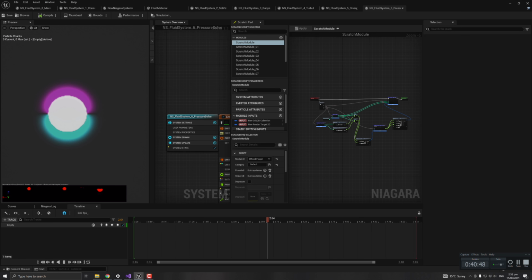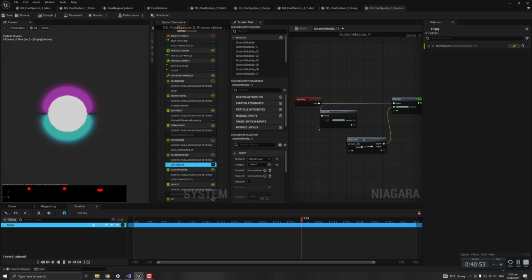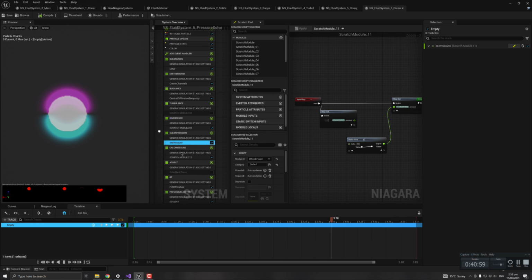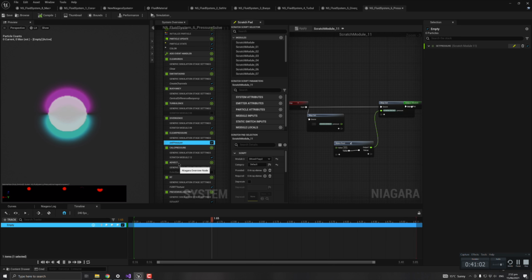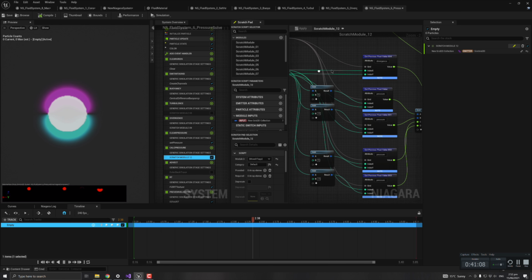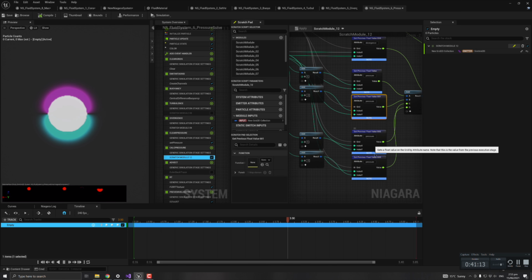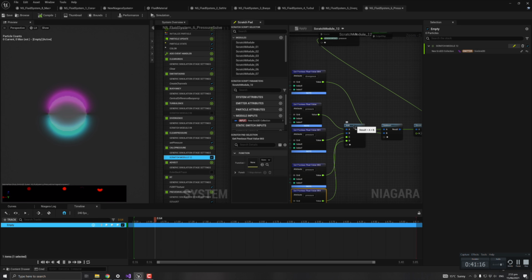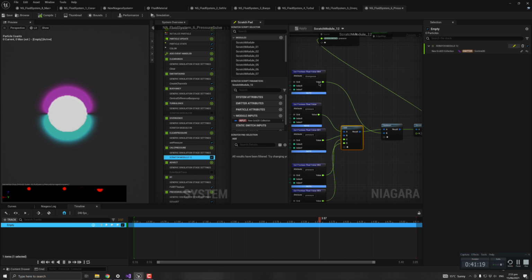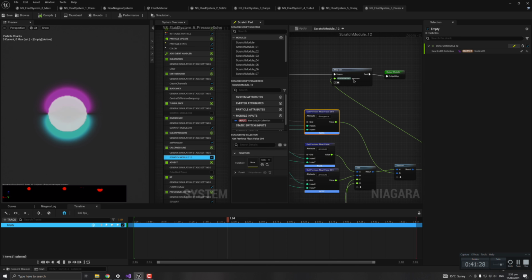So here's what's happening. Let's dive into the pressure solve. I probably didn't explain that the best, I'll probably do a separate video on that. So we clear the pressure, we just set it to 0, and here we go. We sample the pressure at the right and to the left, and above and below, and we add them together, and then we subtract divergence, which, if we had some length scale, we'd have some length scale multiplier here, divided by 4, and then we write to pressure.